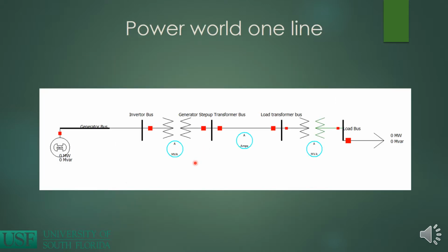Here you can see a one-line diagram, which I used PowerWorld to produce. From this one-line, you'll be able to see the megawatt flow and losses associated with each individual device. The generator in this case would be your solar panels. The inverter will go from DC to AC, and research shows that most of your loss will be due to the inefficiency of the inverter.